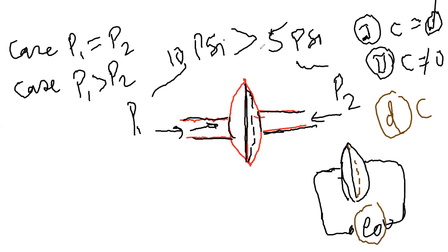So I am going to get some value of E0. But this E0 totally depends upon the change in capacitance. That is, the voltage which I have got totally depends upon the change in the capacitance. But what is the cause of the change in the capacitance? The applied input pressure P1 and the applied input pressure P2. Only the difference is that here my P1 is greater than P2. That's why the deflection of the plate is towards my P2.